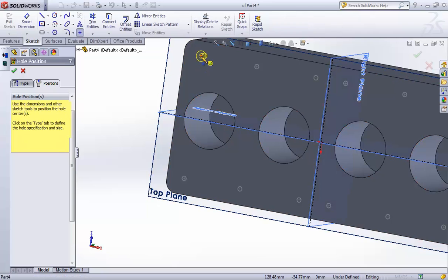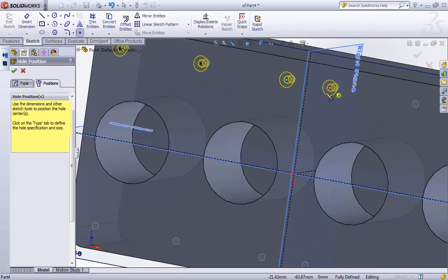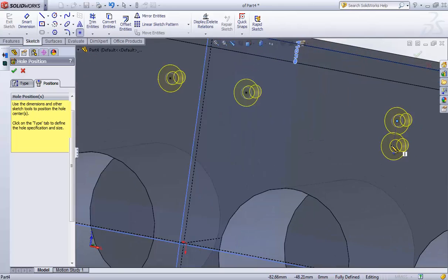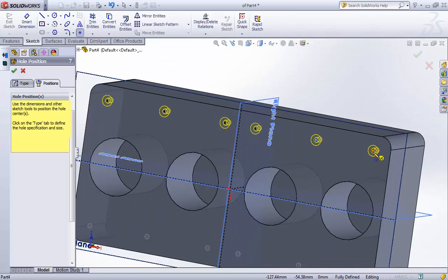It's only a matter of click, click, click. So I'm gonna go click. You need to look out for the endpoint indicator here, so you need to make sure that your cursor comes up with a little confirmation saying you are at that crosshair, you are at the center of that circle there, and that's going to guarantee that you are at the correct location. That's when you click and it gives you a beautiful circle at the right location.